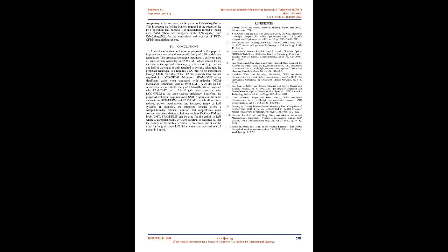4. Conclusions. A novel modulation technique is proposed in this paper to improve the spectral and energy efficiency of LiFi modulation techniques. The proposed technique introduces a different type of time domain symmetry to PAM-DMT, which allows for an increase in the spectral efficiency by a factor of 2, given that half of the signal is only required to be sent. Although the proposed technique still requires a DC bias to be transmitted through LEDs, the value of the DC bias is much lower than that required for DCO-OFDM.